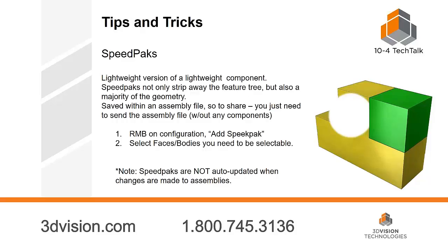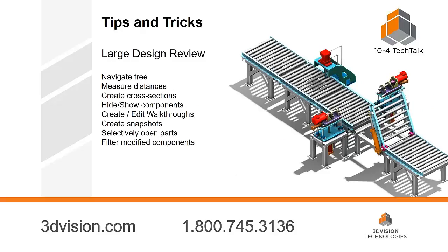transparent. Now a big tip here at the bottom is speed packs are not updated when you make changes to the assembly. So you would have to make it lightweight or turn off that speed pack to get changes to occur in those files. It's graphics only.